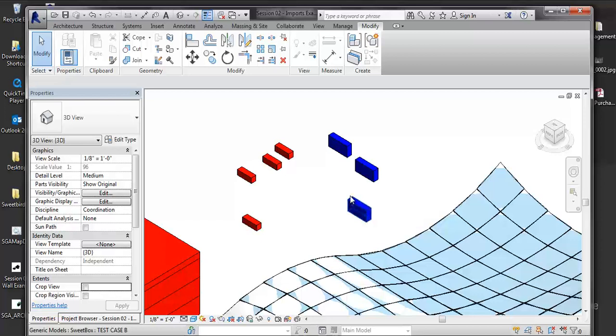So once you turn off box visible, how do you get it back? Good question, sir. You don't. Are you serious? Nope. What do you do? Nope, nope, nope. So that's where, again, nope. It's there. Well, you would set up a schedule. It would schedule as it's still there, and then you would have to use the schedule, the database side of Revit, which we haven't got into, to actually select it. So yeah, it can be dangerous putting visibility parameters on things as well. Be very careful with this.